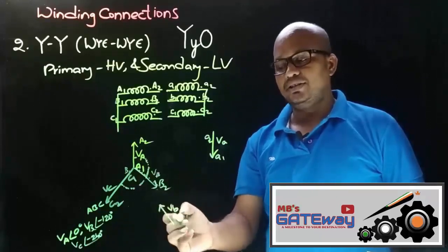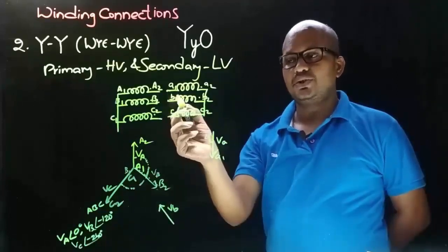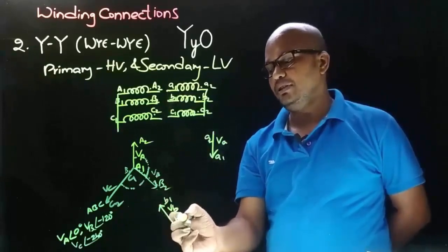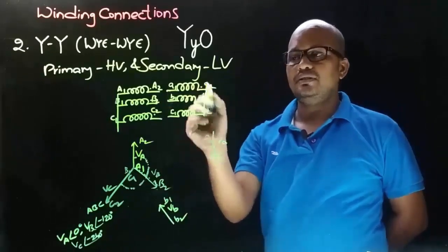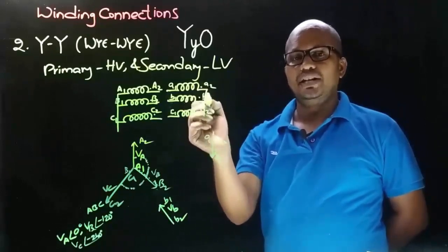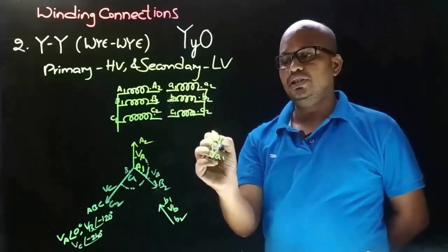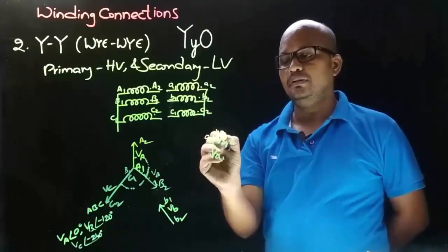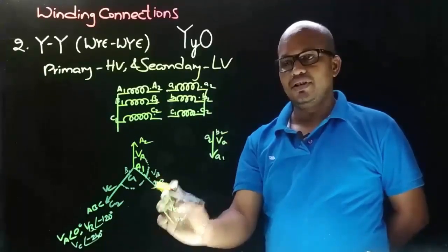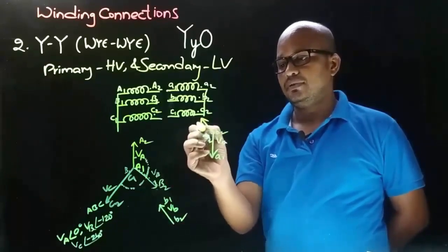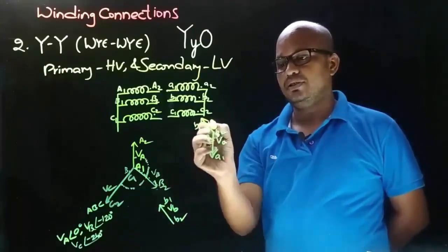And now we need to decide the terminals. As the connection is taken from B1 terminal, the arrow points towards B1 and this will be the B2. And observe in the secondary side winding connection that A2 and B2 are joined together. Means here in phasor diagram, to A2 there will be B2. So this phasor will be drawn like this. This is B1. So this is VB phasor.